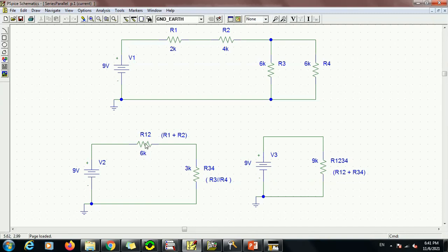Last thing is about the parallel connection. Usually the trade-off is, if we need our loads to have a fixed or constant voltage, then we need to connect them in parallel. So any load connected in parallel would get the same voltage. And if we need them to have the same current, we need to connect them in series.